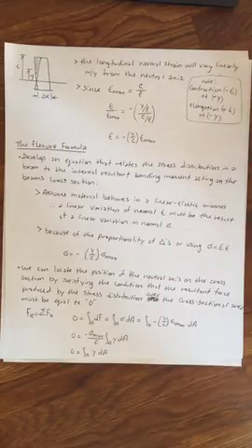So we can locate the position of the neutral axis on the cross-section by satisfying the condition that the resultant force produced by the stress distribution over the cross-sectional area must be equal to 0. So this is what we've done lots of times before. We're just talking about using resultant forces and resultant moments.